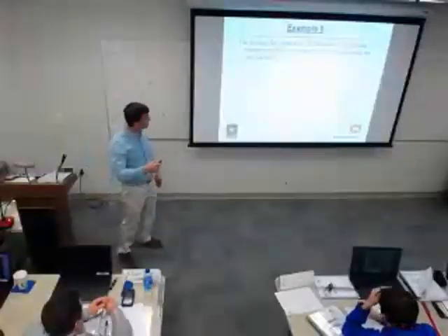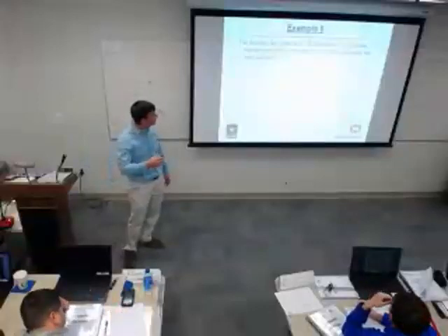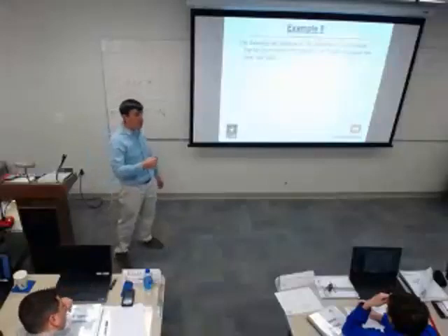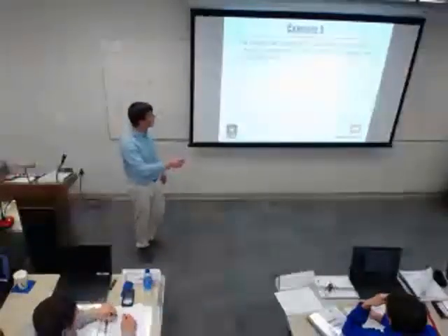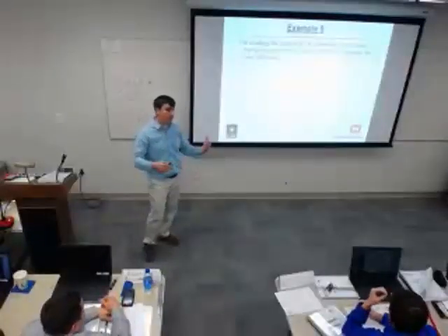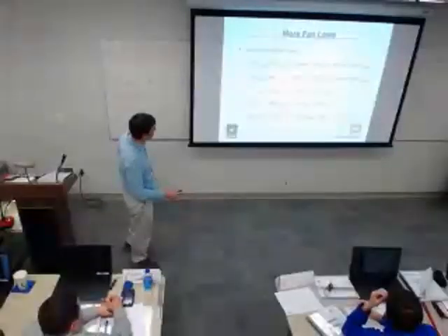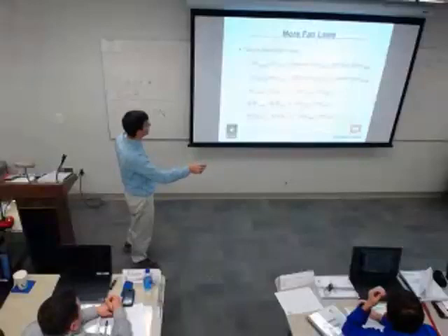All right, please don't look ahead. Existing fan sheave is 18-inch diameter. In this example, we're going to change the fan sheave, and I want to get from 1250 to 1470. That's the number that we just calculated. Let's go back a little bit. I'll show you that number. So here we are.